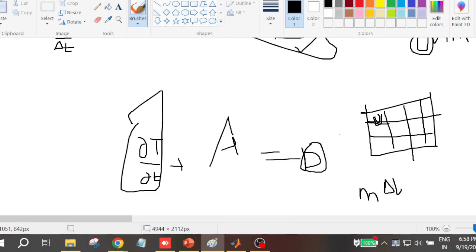Now once I have a lid driven cavity problem, I know the lid velocity, say for example 1. Based on this I'll guess what will be the maximum internal flow velocity. That will depend on the lid velocity. If the lid velocity is 10, I will have somewhere around 15 meter per second within the internal flow, and I will take that as the velocity scale.